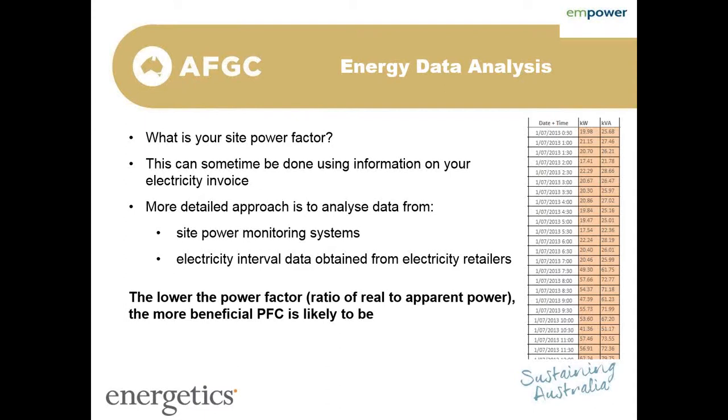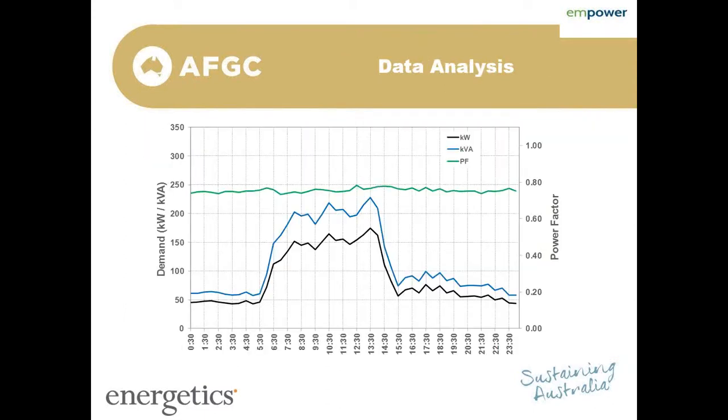The take home from that is that the lower the power factor, which again is the ratio of the real to the apparent power, the more beneficial power factor correction is likely to be for you.